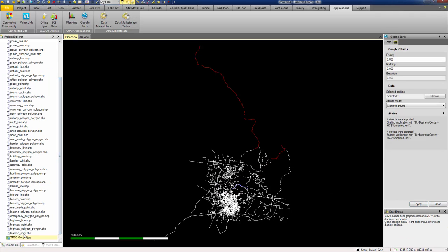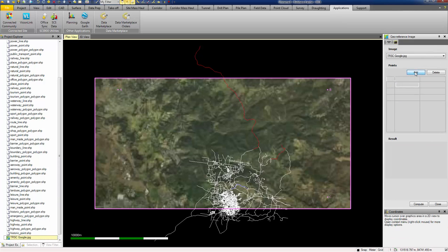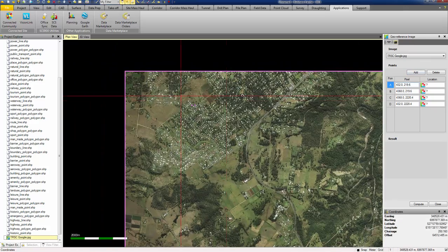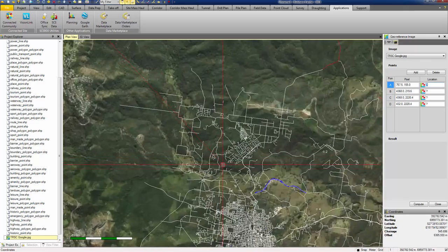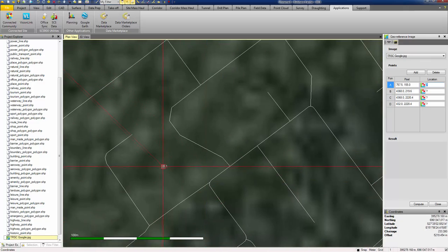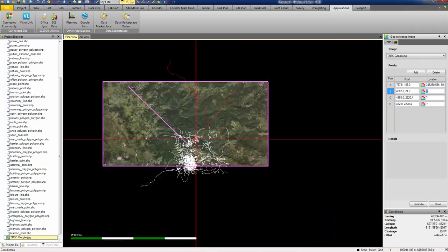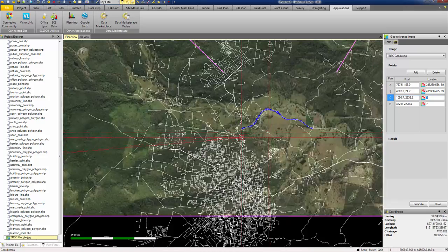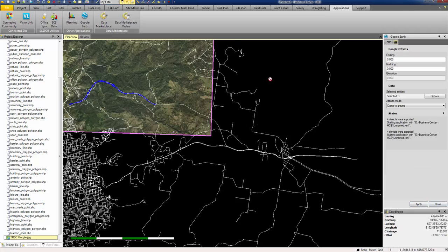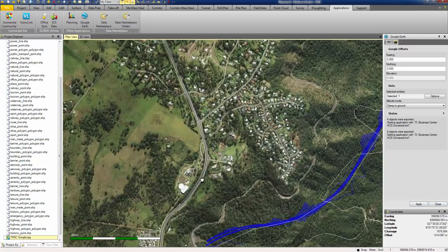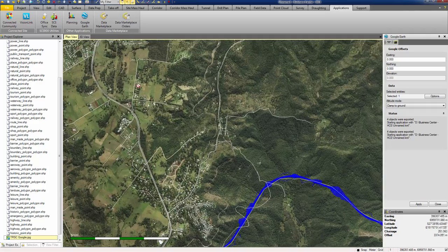And I'm actually going to use a geo-reference, which allows me to define some coordinates. I'm going to use 4 for the 4 points I've done. I can go and find these points. I'll graphically pick the pixel and then select the point that I used to export, and I'll repeat for all 4 points. And I'll register that. And you see now our image lines up perfectly with our open data and our project.